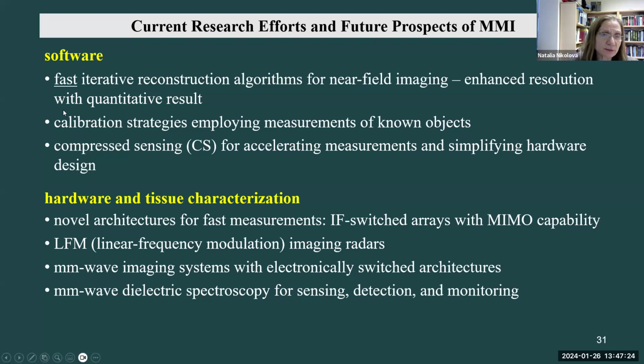Another very interesting, in my opinion, research effort is in devising calibration strategies that employ the measurements of known objects. Those can not only lead to better de-embedding strategies where the background signals are de-embedded more effectively, but they can lead to reducing clutter, radar clutter, which is very strong in medical imaging situations, and may even enhance the resolution.